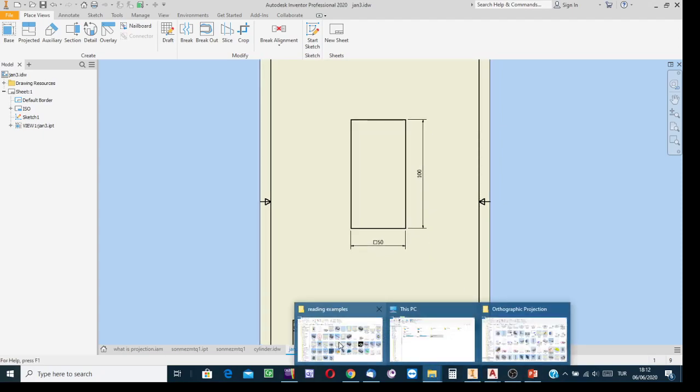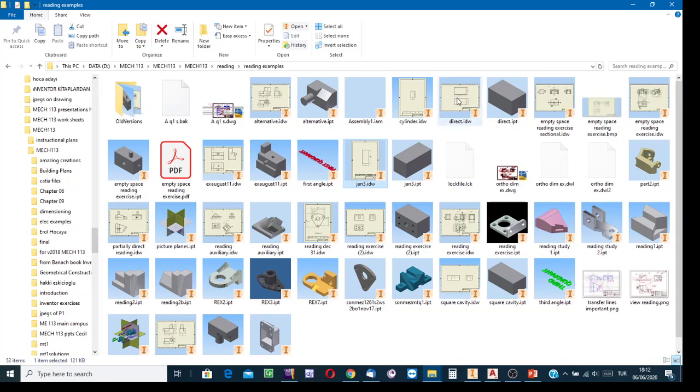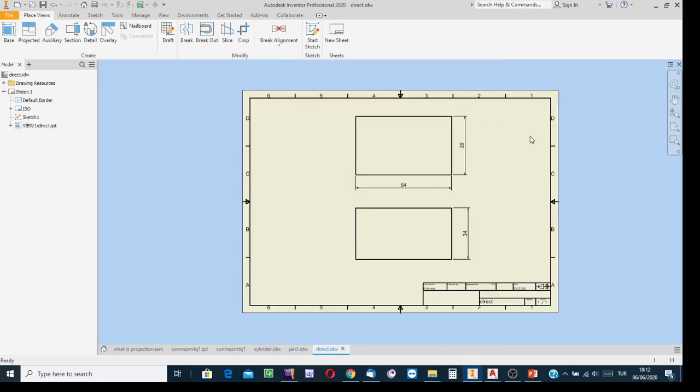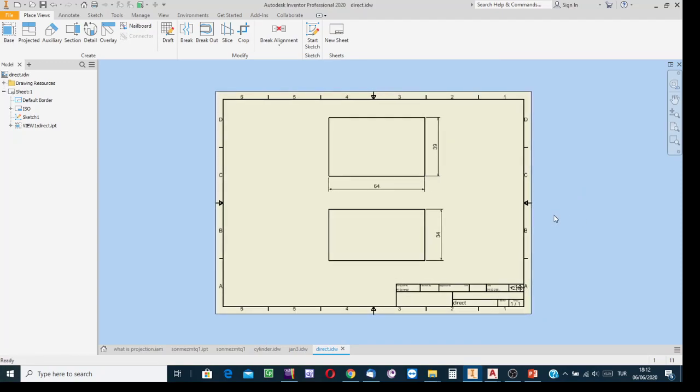Another reading example. Okay, now in order, bring this sheet to your interest and then achieve reading. What is the object in shape and also in size? If there is not one view but more views, in this example 2 views, yes, the quadrant symbol is extremely important. The first thing to do is to refer to the title block and see which quadrant has been selected for these orthographic views.